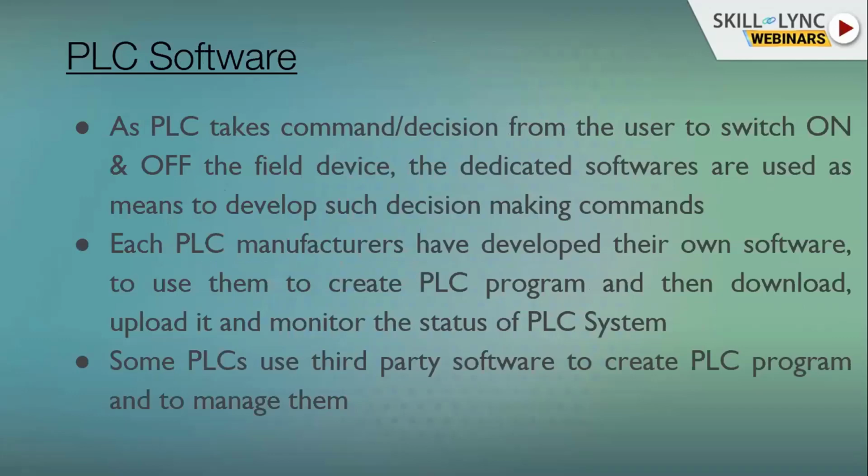So let's have some idea on PLC software which is used for PLC programming. PLC software is something where we put our commands and decisions together to let the processor know how we want the machine to run. We will have many instructions like relay type switches, NO, NC, or timer, counter.